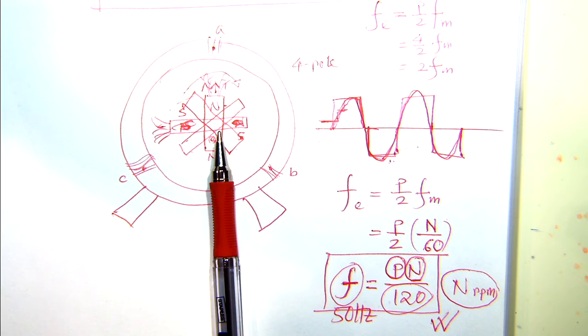So depending on the number of poles we buy from the manufacturers, it will operate at a certain speed as well, because we have to supply a constant frequency. Now the whole set will come together, that is how strong your prime mover has to be to rotate that machine. But as you increase the size of the machine or number of poles, definitely it will be heavier, and all of those issues will come anyway.